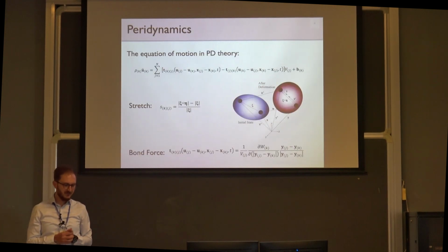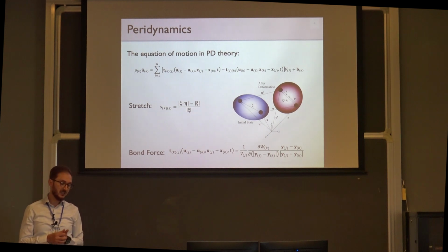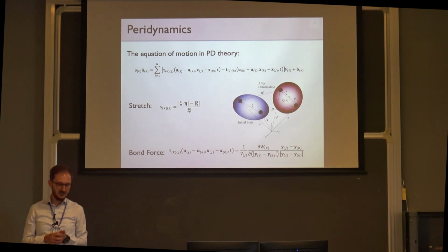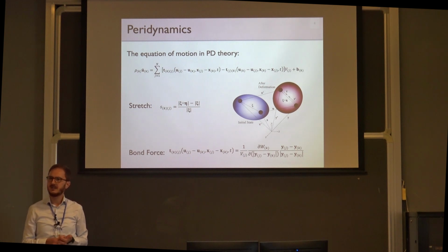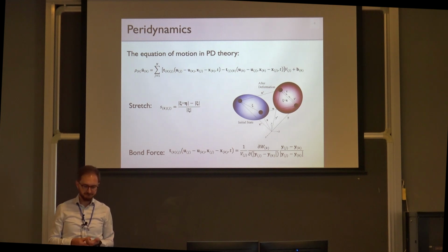This is the fundamental equation of motion of peridynamics. The theory uses integral equations that can be applied to any kind of discontinuity, such as cracks. That is why we can use peridynamics in crack modeling easily. And this is the discretized form of the equation of motion.